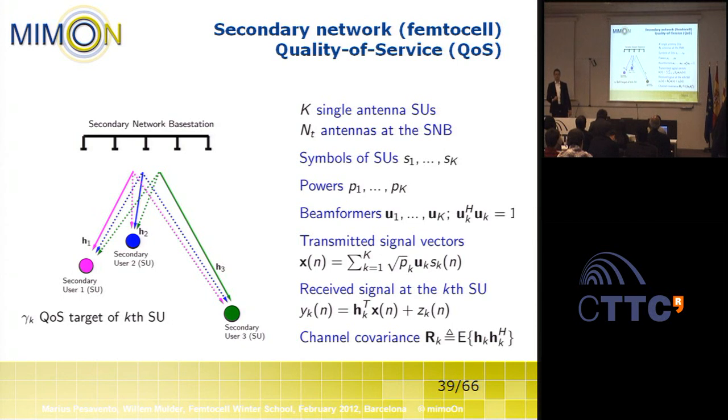as illustrated before. So there's feedback between the receiver and the transmitter, or it could also be acquired from the uplink transmissions. So if we have a TDD system, time division duplexing system, so uplink and downlink are performed on the same frequency resource, then these channels can be estimated from the uplink transmission at the base station.